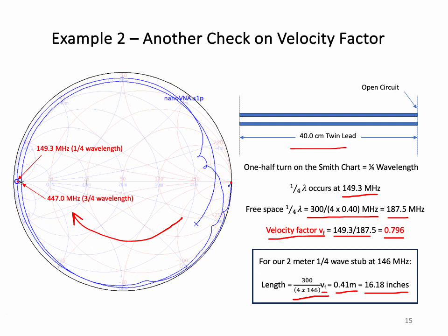The fact that this rotation starts to move inwards with frequency, as we see here, the lines keep closer and closer to the origin, is a consequence of the losses that exist in the transmission line. The lossier the line, the faster the impedance trajectory spirals in towards the center. What this also says is if you have a very, very poor SWR at the terminals of your antenna, a very long, lossy coax run will mask that fact, making it look like your SWR is great, even though little to none of your power is actually making it to the antenna or is being radiated.